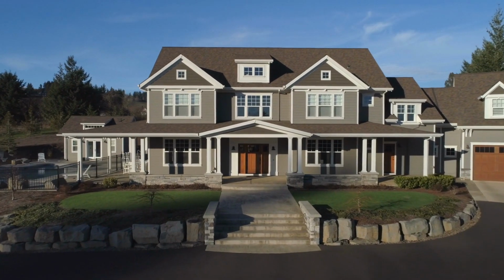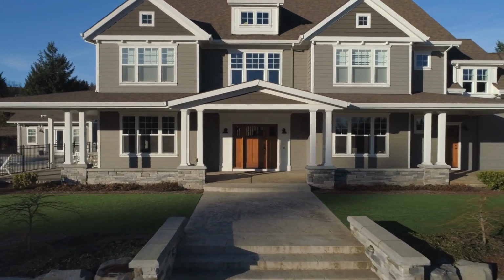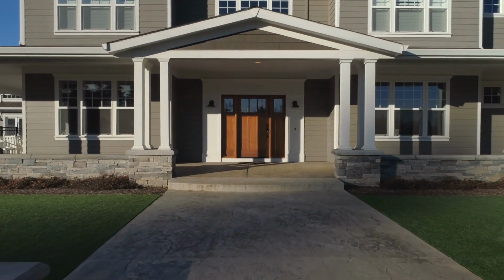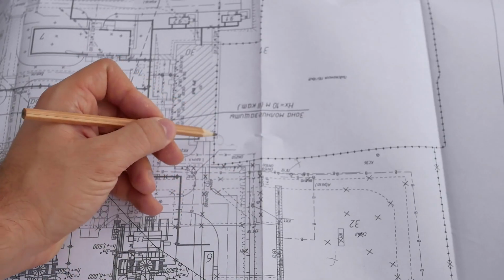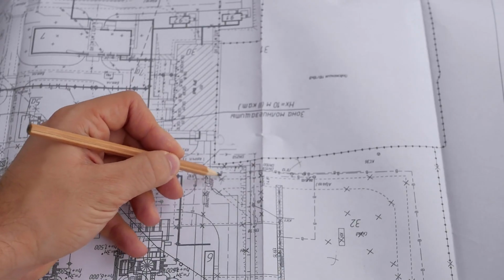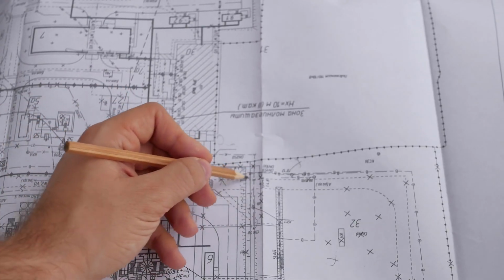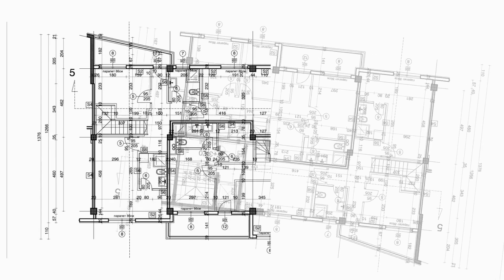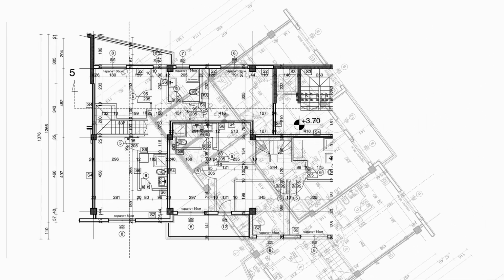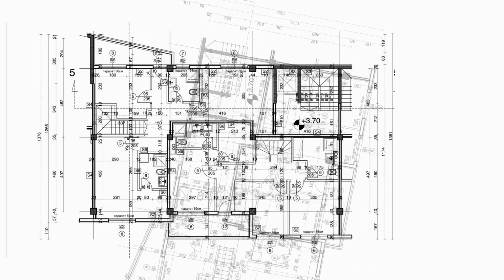Although the name might give it away, as-built drawings are created to show final in-situ conditions on the project once it's finished. Essentially, as-built drawings depict deviations and changes that have occurred from the approved set of design drawings, as well as any deviations from the approved shop drawings. To put it simply, as-built drawings show what's actually been built once construction is already done.